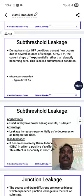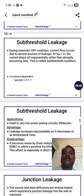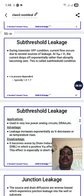VGS less than VT means that the voltage is very, very minimal. Already the threshold voltage itself is very small, about 0.7, but compared with the threshold voltage, this gate to source voltage, the input voltage, is very low. When the input voltage is lower than the threshold voltage, at the beginning stage of the transistor before the switch is on, in the off condition, several leakages happen. Those leakages are called subthreshold leakage. This is called the subthreshold condition.